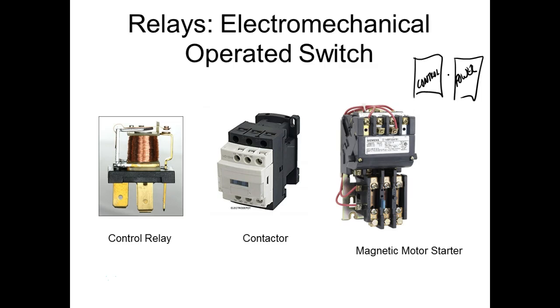So we can have a control section where most of our relays and stuff are, and we run low voltage there. And what's the advantage of low voltage over high? Safety. So with 24 volts in a control cabinet, you wouldn't have to wear any special PPE. You'd wear standard PPE that's required by your company. Most people require you to wear safety glasses. A lot of people wear hard hats, long pants, right? Leather shoes. Some people have to wear steel-toed shoes or metatarsals, but that depends on the company.